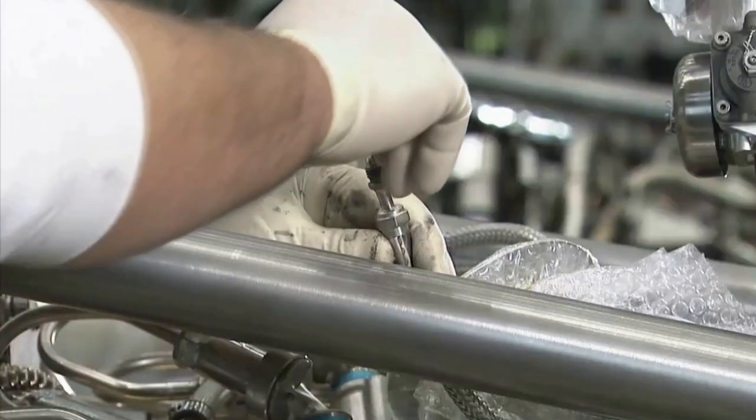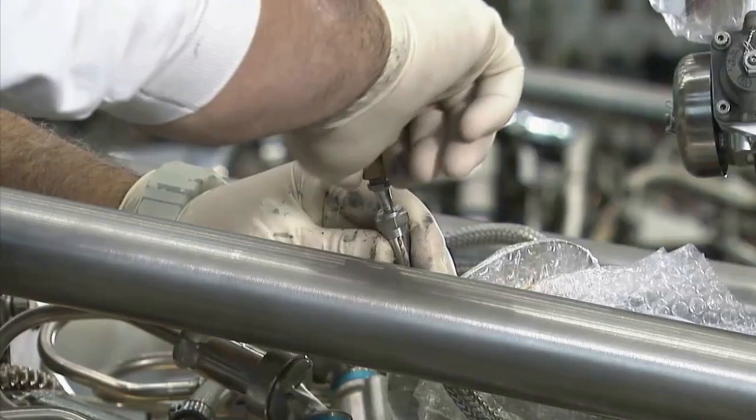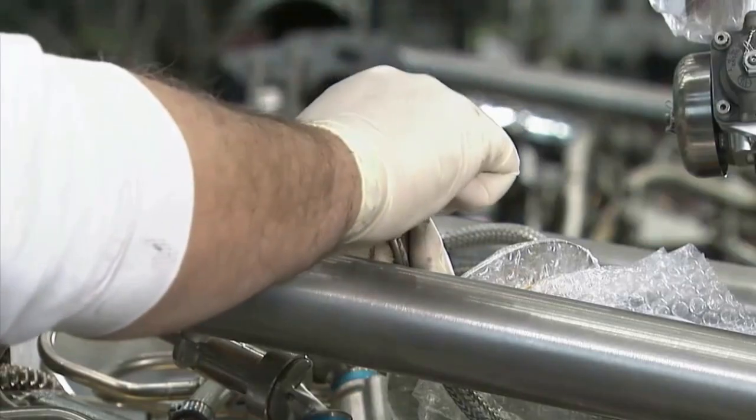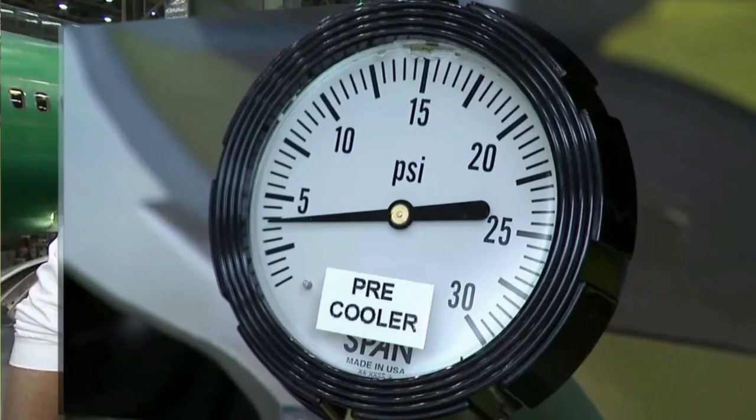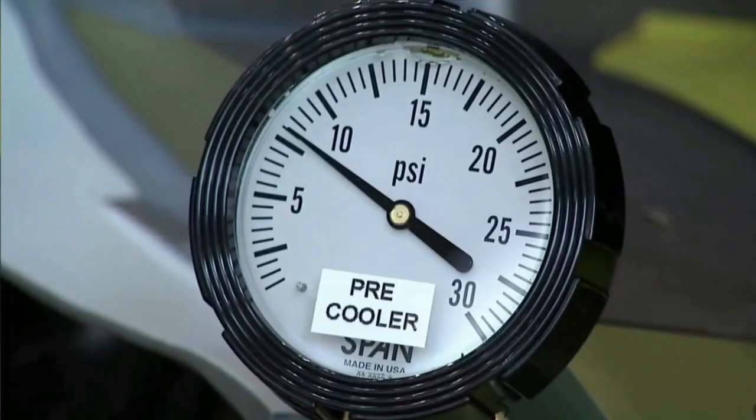If the control pressure is still low, the problem is with the PCCB or its control line. If the control pressure is now good, either the 390 sensor or one of its control sense lines is leaking.